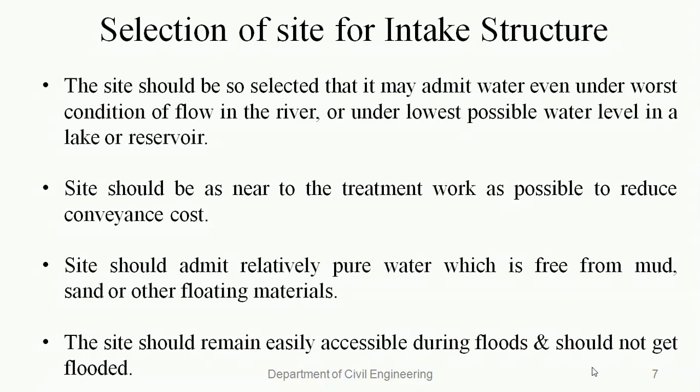Point number 2. The intake site should be as near to the treatment plant as possible in order to reduce the transportation cost. The intake site should admit relatively pure water, which is free from mud, sand, or other floating materials. This means the intake must be located in the pure zone of the source so that best possible quality of water is withdrawn for our usage.